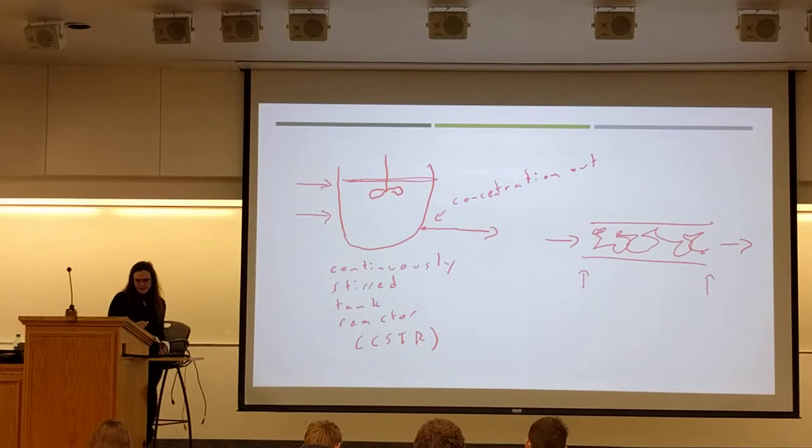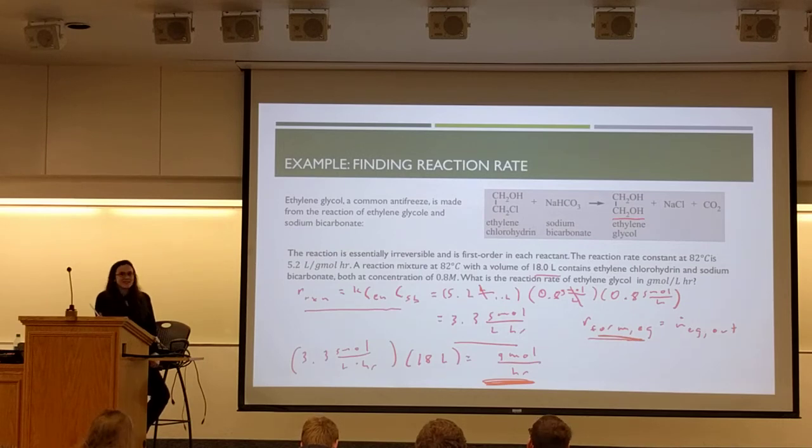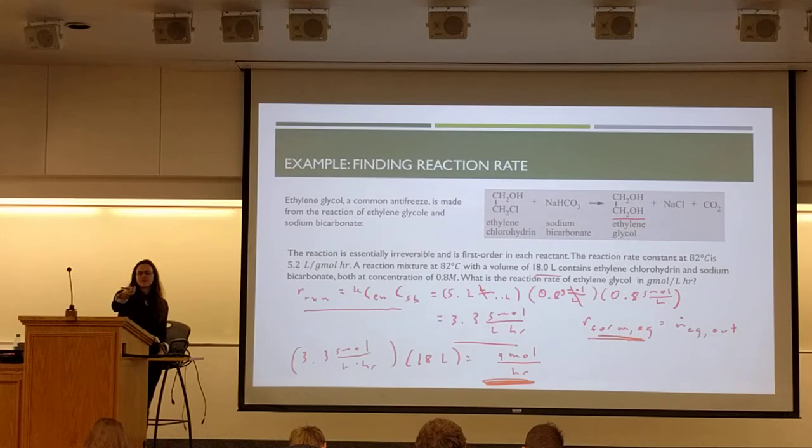How about fluid flow? How do you think fluid flow is related to this situation right here, where we have this reaction happening in a big reactor? Yes? With the bottom equation, how you have the reaction rate times the volume, if we were to increase the volumetric flow rate, we would increase the rate of production. So the volume in there is the volume of the reactor vessel, so that doesn't change with the volumetric flow rate. But the flow rate coming in could obviously change your concentration because it would be carrying reactants and products in and out at different speeds. Yes? You gotta get it there somehow. What kind of machinery would we use to get it there? Pumps. I love pumps. You've had 2 labs where you use pumps so far, so you're beginning to learn.